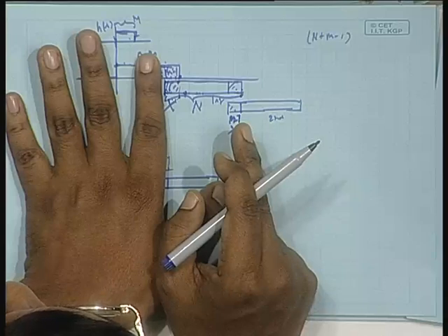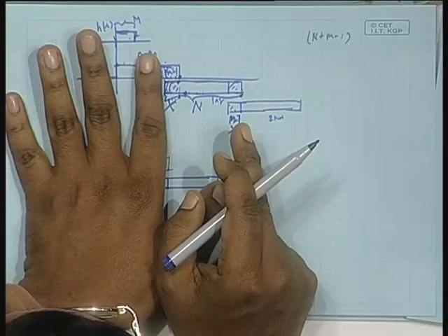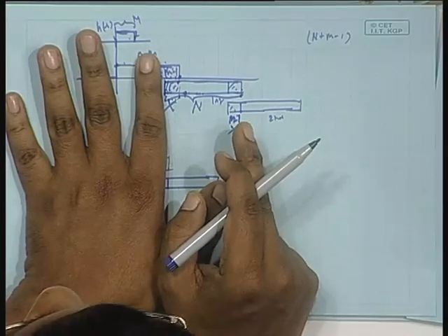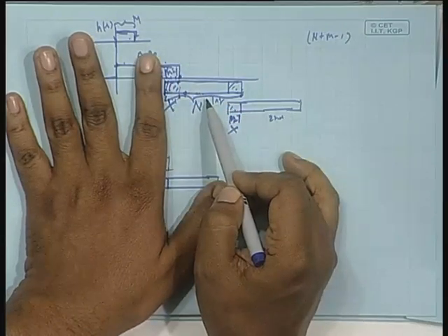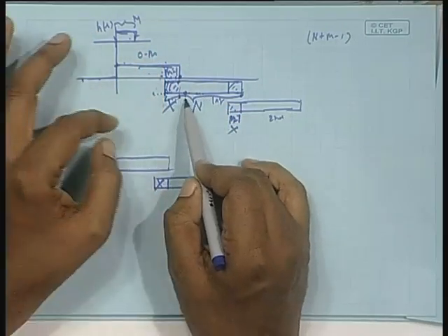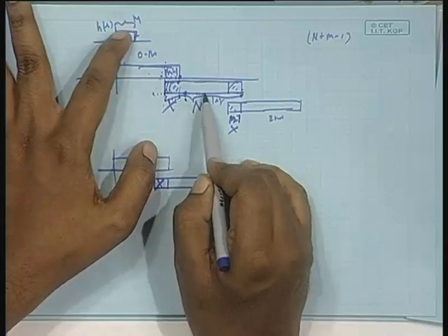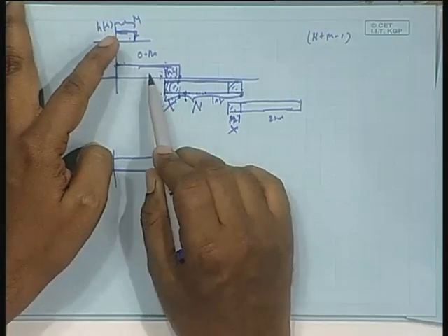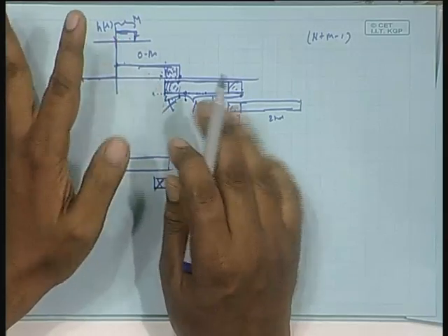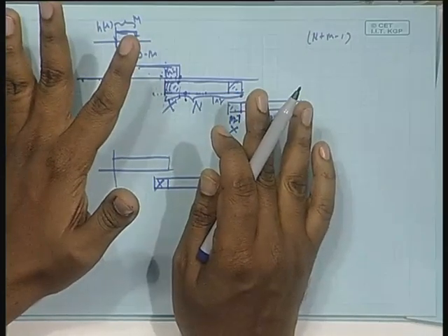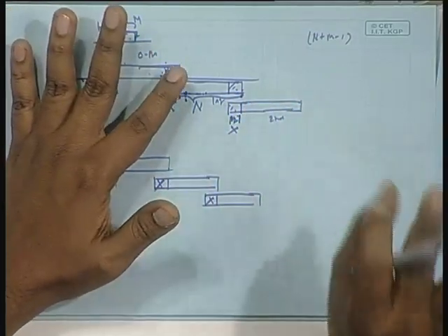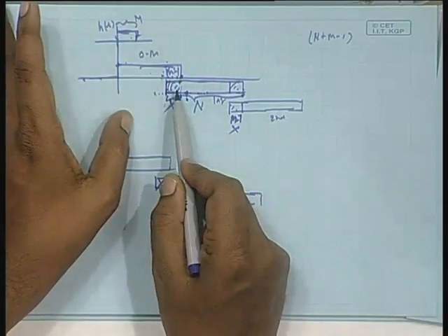From the Mth point you get the real linear convolution result between this block and this block, and that is what I want, because from this point onwards convolution between this and this is enough. I do not need any data from here, is it not? So two things are matching. There are also M minus 1 points you have to ignore, and I am already ignoring them.